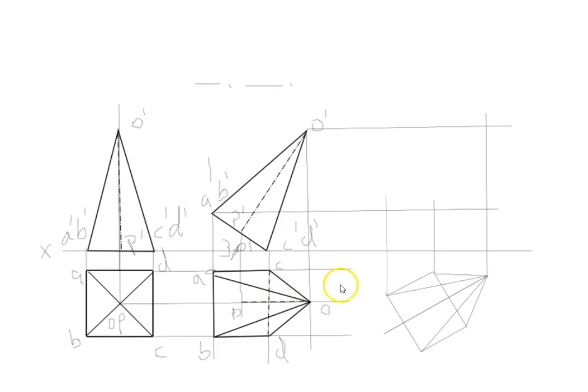So here I have drawn this top view in tilted position. I'll quickly demonstrate how this is actually done. A couple of things you have to be careful about: the first confusion people normally have is where to start, how to start drawing this, which point to start tilting from. In this case it is a simple one, since the axis is parallel to this edge, with respect to which we are tilting it, so we can easily draw this axis.